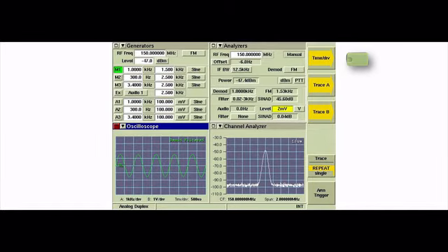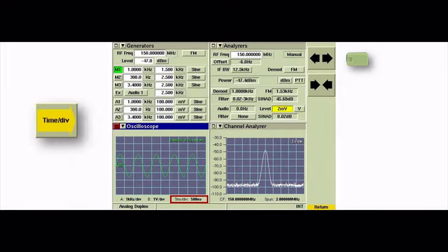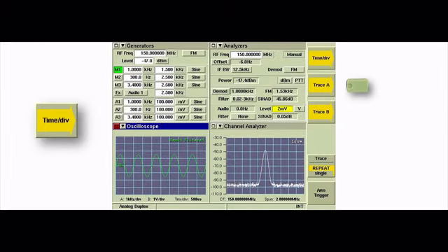With the oscilloscope tile highlighted, control soft keys will appear on the right. By selecting the time per division soft keys, then using the expand and contract soft keys, the horizontal time per division can be adjusted. By pressing the return soft key, it will return the user to the main soft keys.